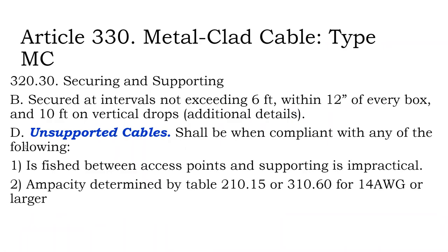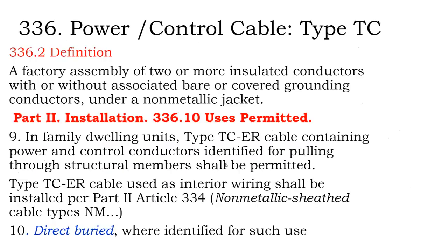All right, so now we have some more rules for metal clad cable. Secured at intervals every 6 feet, 10 feet for vertical drops, within 12 inches of a box. I guess you don't need to attach it to every single rafter as you're going across the rooftop.